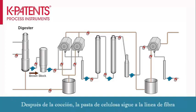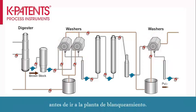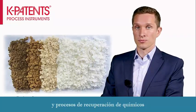Following the cooking, the brown stock moves on to the fiber line, where it passes through a series of washers to remove as much dissolved solids from the pulp as possible before it goes to the bleaching plant. The cleaner the pulp, the fewer chemicals are needed in the following bleaching and chemical recovery processes.